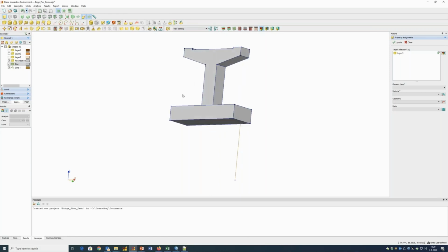So as I said, to create the other piles, we are going to use array copy. So I select the pile, and first I'm going to copy in the Y direction with an offset of 1.43 meter, and I do it 2 times. So immediately see the preview option of this copied action. Click apply, and it results in 2 extra piles under the shade tree.